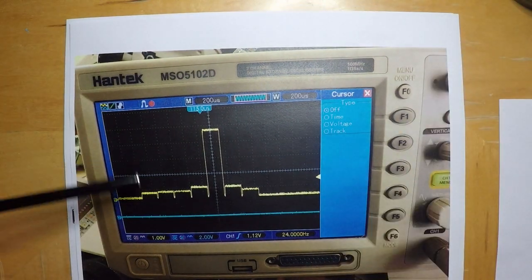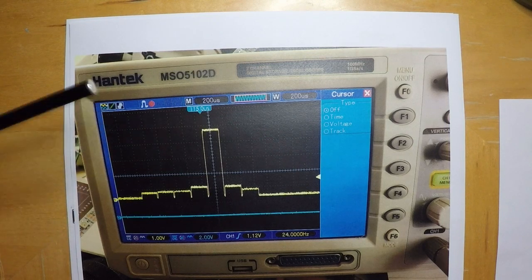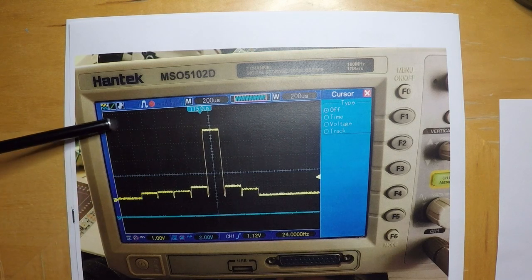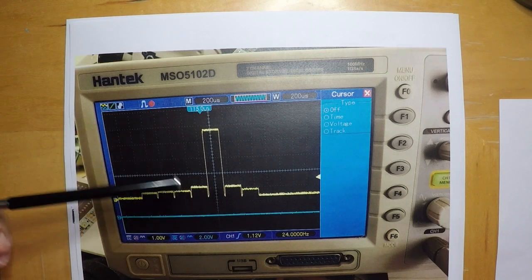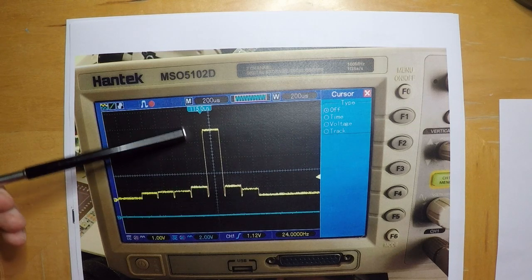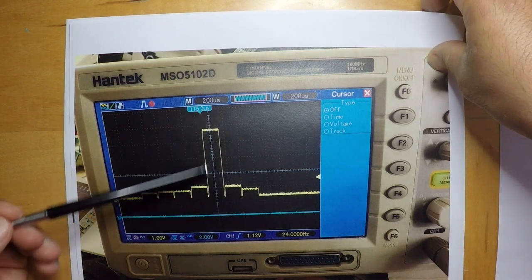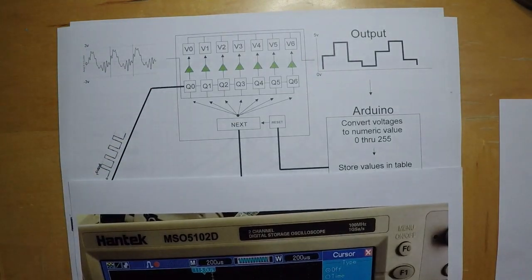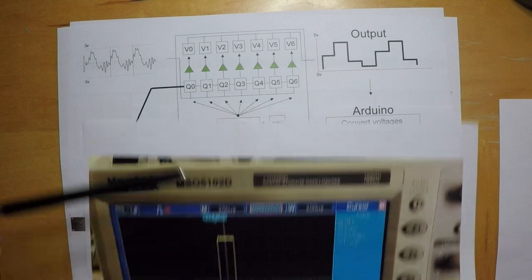These are voltages. Here's the 0 line, and this up here is 5. Well, it's probably a little bit less than 5 because it wasn't at maximum loudness, but the 5-volt line might be up here somewhere. Each one of these little squares should represent a volt. So this is like 1, 2, 3, 4. It's a little bit less than 5 volts here. So this very tall column represents, let's see, that would have been on 1, this would have been on 0, 1, 2, 3, 4.